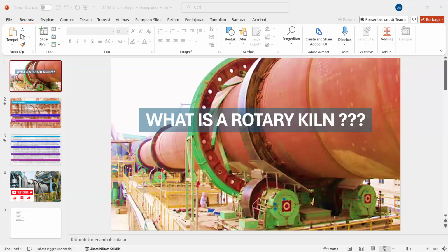Temperature difference between the top and bottom of the kiln may cause the kiln to warp, and the refractory to be damaged. Hence, normal practice is to provide an auxiliary drive for use during power cuts. This may be a small electric motor with an independent power supply, or a diesel engine. This turns the kiln very slowly, but enough to prevent damage.